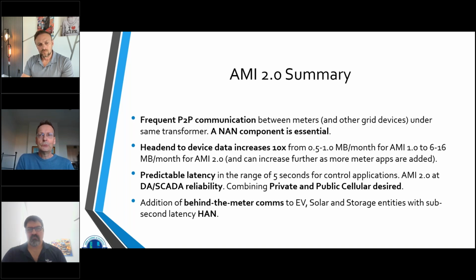And we didn't talk too much this year in the UVA activities about behind the meter comms. This one is essential though. In some of the use cases, like the EVSE management that Carson was describing, sub-second latency is required on this home area network. And so far you see mostly usage of Wi-Fi there, but as Oleg was mentioning, PLC type of communication can also be very strong in this area. So that's a little bit of summary.